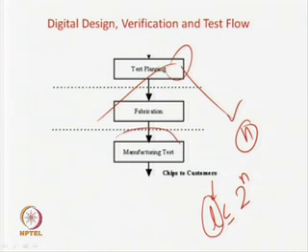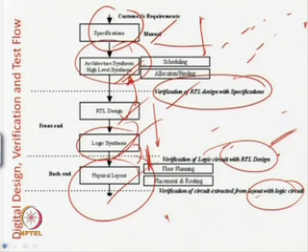Now, once you have your circuits ready, after fabrication you will get your circuits, and you have to test them using these test patterns. Whatever chips you find that do not have any defect, you give to the customers, and faulty chips you can throw away, because we will see at the end of the course, in the testing module, that repairing is not a very essential part of VLSI testing. So, we will see that. That is basically the design verification and test flow for digital designs.